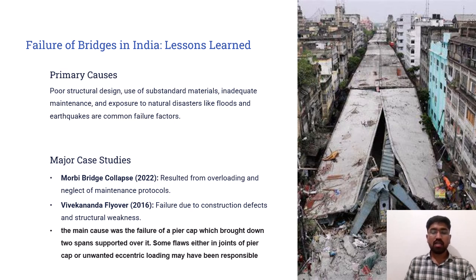The shuttering and staging system failed as it lacked sufficient lateral bracing and was improperly aligned. The temporary supports were overloaded and not designed to carry the fresh concrete load adequately. Additionally, construction sequencing was mismanaged with multiple spans. The collapse was a result of combined structural instability, lack of safety margins in staging design, and inadequate site supervision.